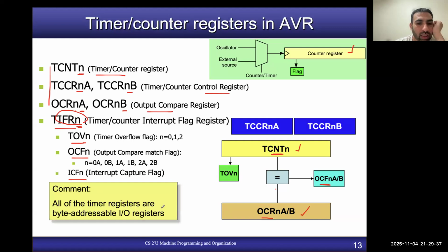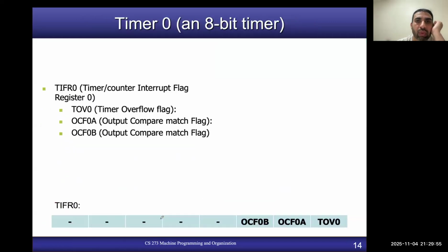All of the timer related registers are byte addressable IO registers, and they are within the standard IO address range. Which basically means that you can use in and out instructions with them to access them.